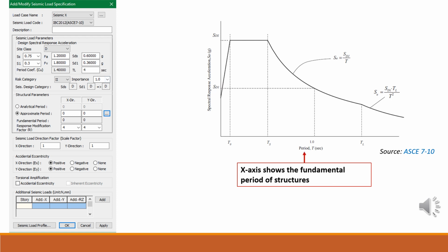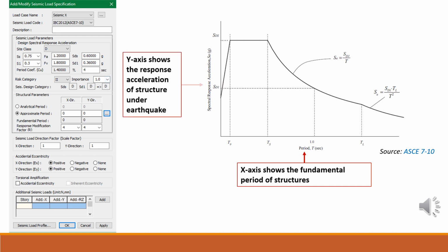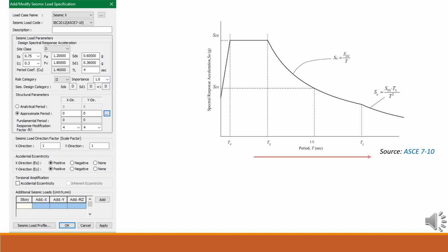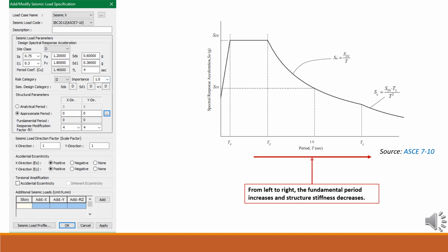The X-axis shows the fundamental period of structures. The Y-axis shows the response acceleration of structure under earthquake. From left to right, the fundamental period increases and structure stiffness decreases.